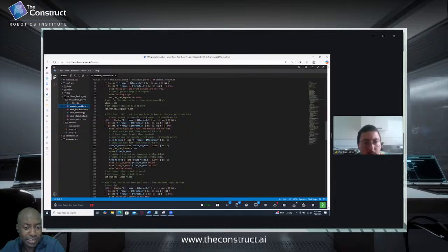So we calculated a distance to move based on what the front range was getting minus the threshold. This was the distance to move. We don't want it to move too far, because just because it's free for the immediate range doesn't mean it's going to be free permanently. So then I decided to go with 0.1 meters per second. It seems a reasonable speed and prevented any hard braking for the robot.